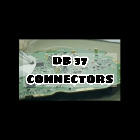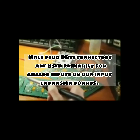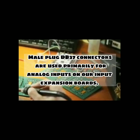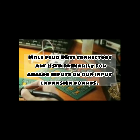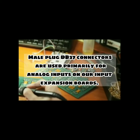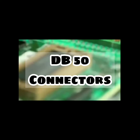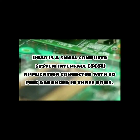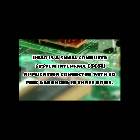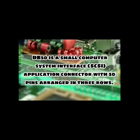The fourth is the DB37 connectors. Male plug DB37 connectors are used primarily for analog input on our input expansion boards. The last from the DB connectors is the DB50 connectors. DB50 is a small computer system interface, or SCSI, application connector with 50 pins arranged in 3 rows.